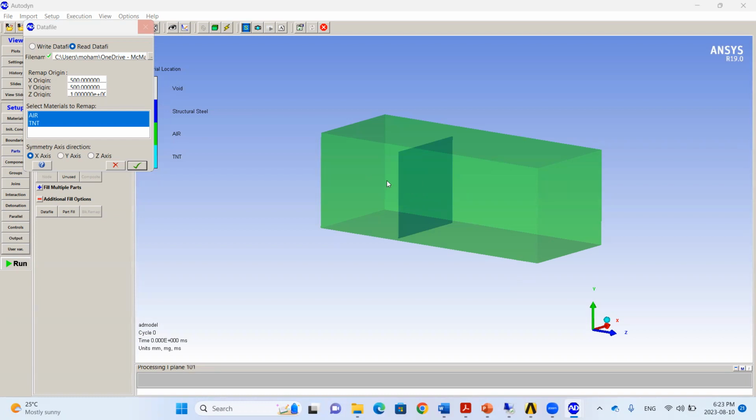So if we put pressure gauges behind the steel plate, we can calculate the pressure behind the steel plate and see what is the value of the generated pressure waves and the reflected pressure waves behind the steel plate. And we can put any gauge at any element on the steel plate and calculate von Mises stresses, strain, displacement, whatever. Now we have our fill completed.